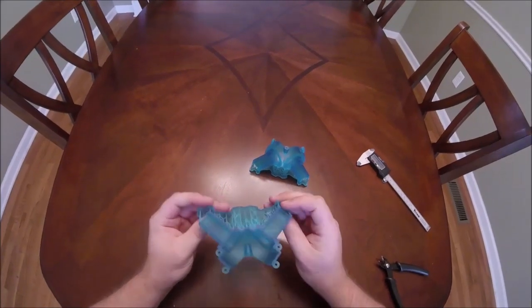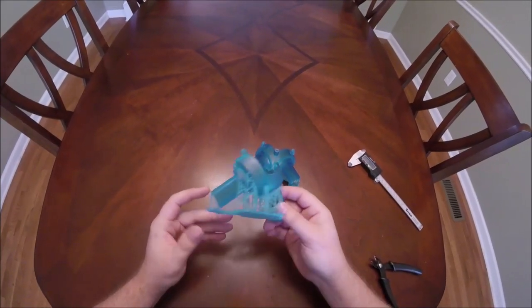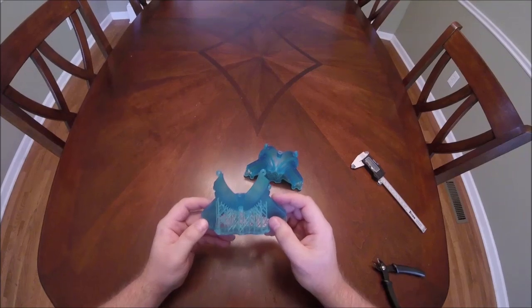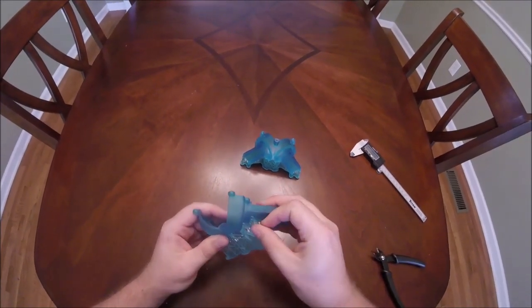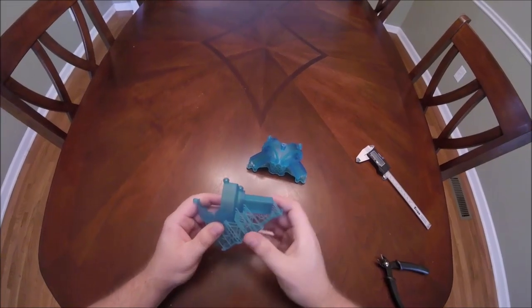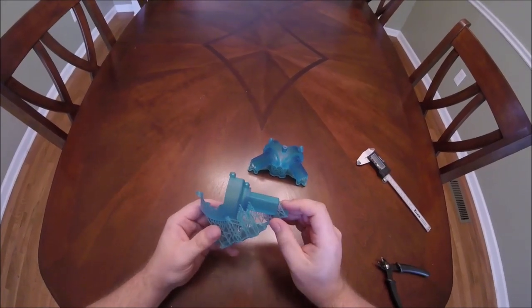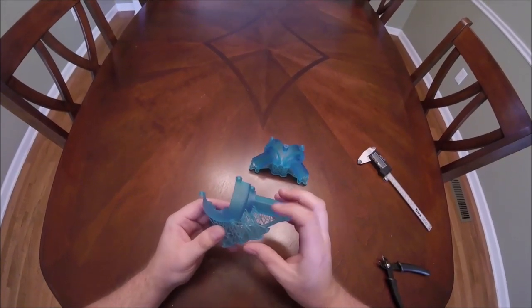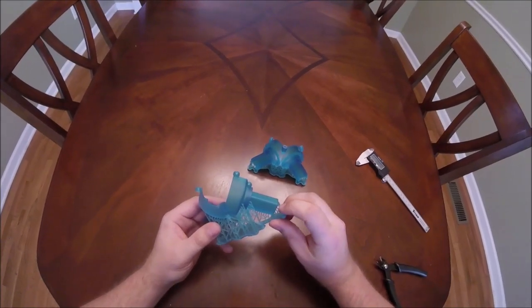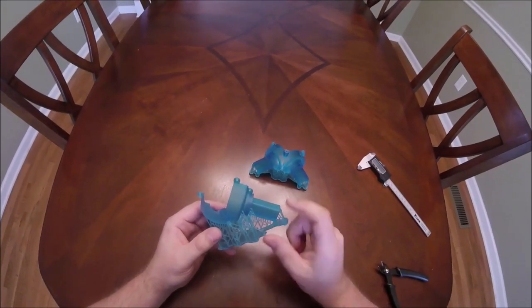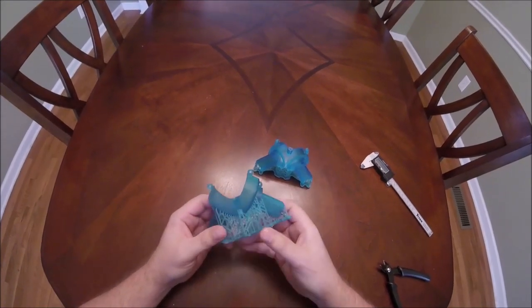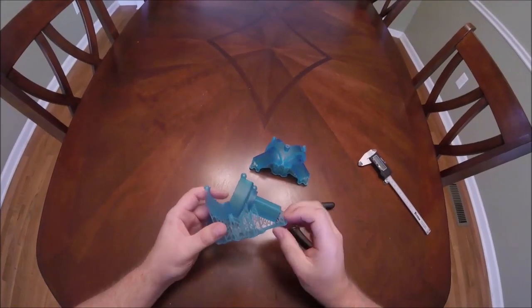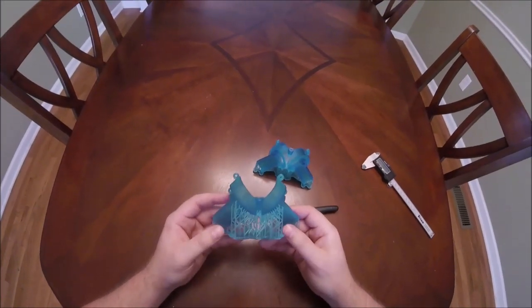For me, it really depends on the type of model I'm doing. For something like a larger sort of engineering part like this, really I'll just be removing these supports in bulk, and you can see if you actually fatigue them a little bit, they kind of just break right off. The only thing to really note when you're just sort of breaking them off is that the support points will scratch the part. So you should think about which way you're pulling on the supports, and maybe remove supports manually with some clippers in places that could end up dragging across the part and scratching it up.